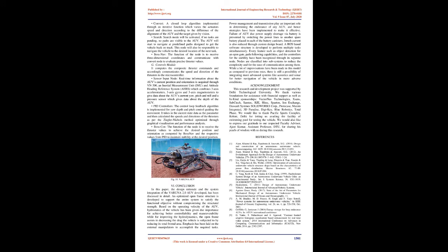As shown in [14], we use a parallel PID loop configuration. e(t) denotes the error between the current and desired state, and u(t) denotes the RPM of the thruster. The P term is proportional to the current error value and multiplies it with a gain factor Kp. The error value is calculated by subtracting the process variable from the set point and then multiplying this value with Kp. If the controller is only using the P term, then this value defines the output of the controller. If the value of the gain factor is large, then it will increase the speed of the control system response. But if it is too large a value, then it will overshoot and the process variable will oscillate.